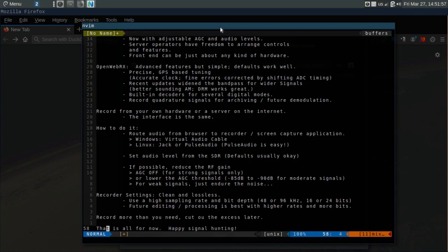In fact, if you're making a recording for an archive or to share with other people or for a documentary or news report, that constant pumping of the background noise when there's a strong signal is unpleasant, and it can be avoided if you turn the AGC sensitivity down so that the background noise level stays low.